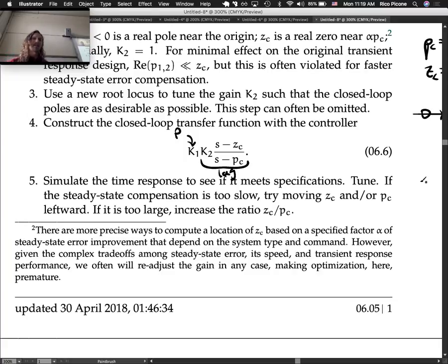Typically instead, we're going to take that encoder measurement and turn it into a digital signal. I have a pin 7, maybe that's my encoder pin, and it gives me the current position of the motor. I take that, and the user says, I want 30 degrees. It's giving me 20. I compute then what the controller gain times the error is. So 10 degrees times maybe the controller gain of 5.